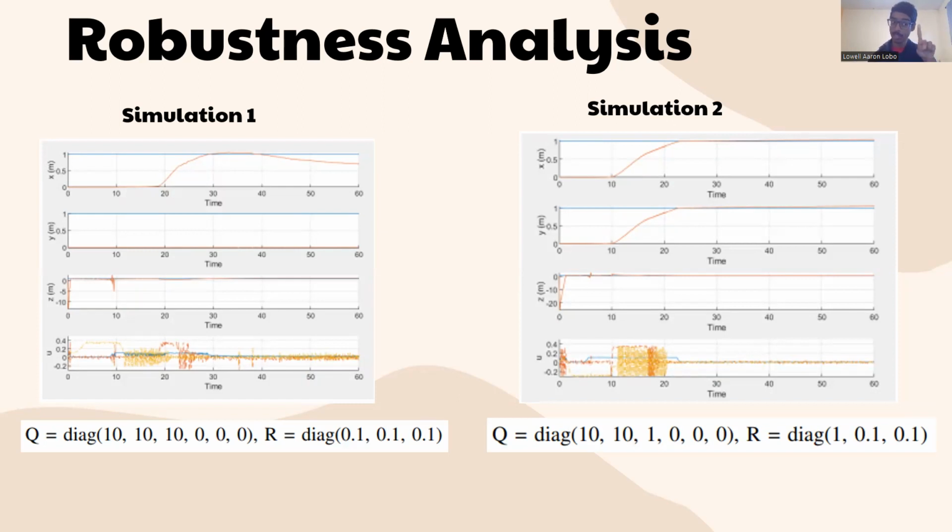Also important to note, and this will come later: in our weight matrix R for the control input, the first one is our S value, which is the arc length, and the second one is our theta value. We gave more weight on the arc length, and therefore it shows a good result.